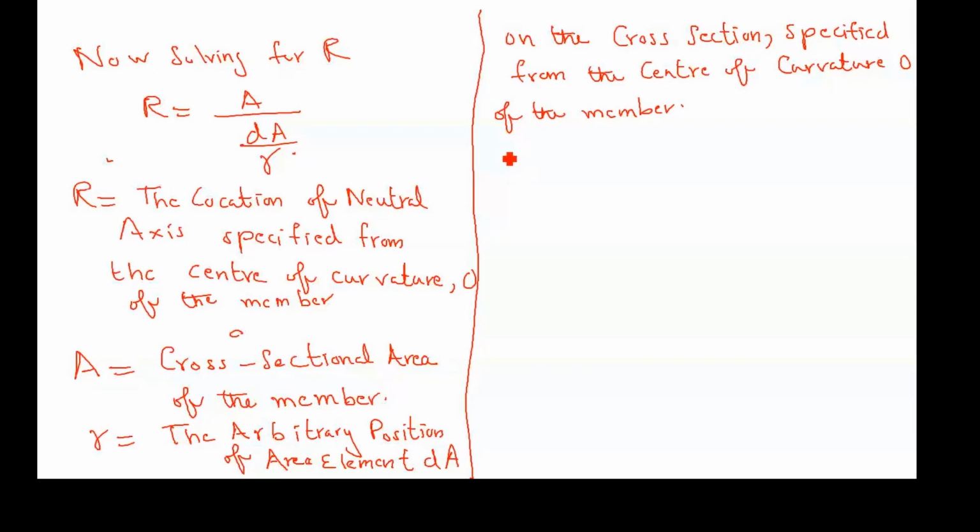Now dF is equal to stress into dA, and dM is equal to dF times y, which is equal to stress into dA into y.